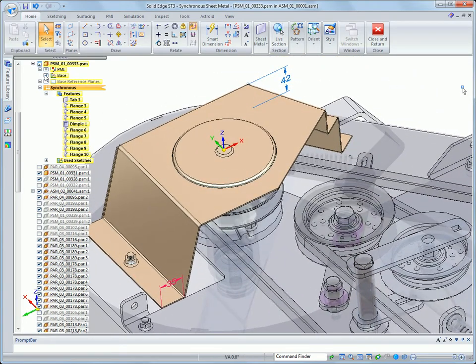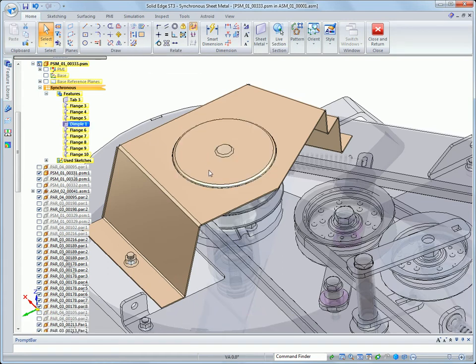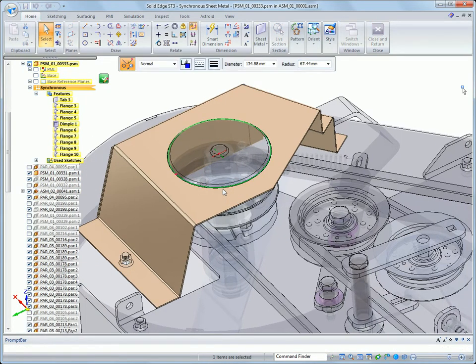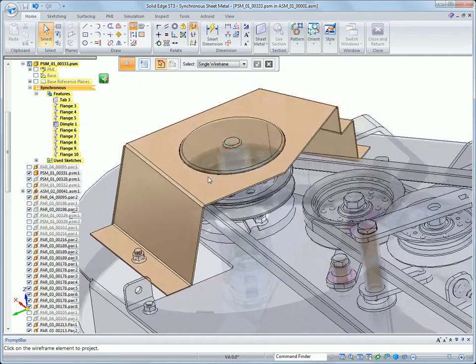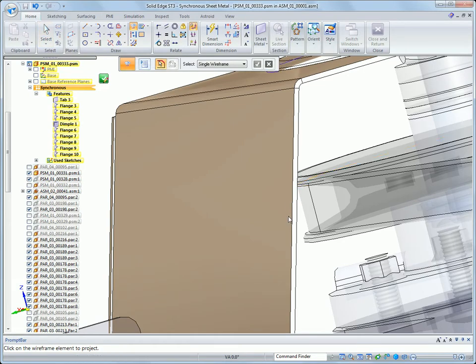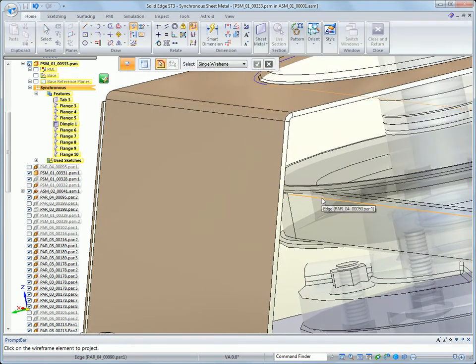Because the dimple is a procedural feature, we can edit its profile to drastically change its shape. And in this case, we're going to even delete the original profile and create a brand new one. We're going to use the project to sketch command to project the edge of the belt up to the profile plane for the dimple.